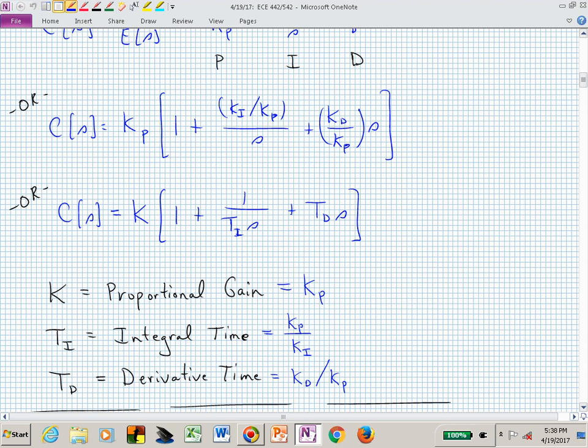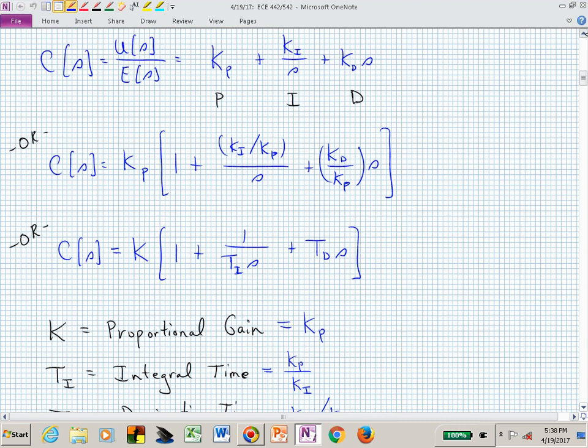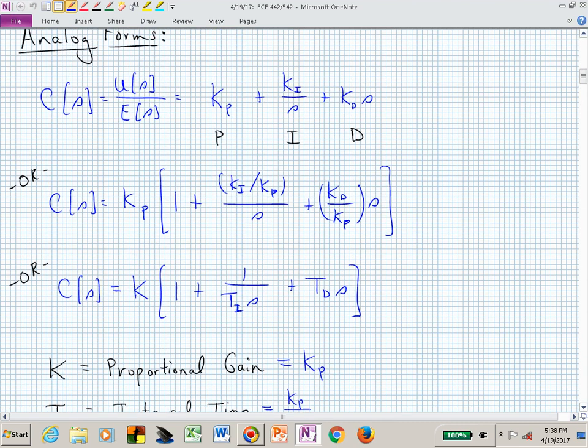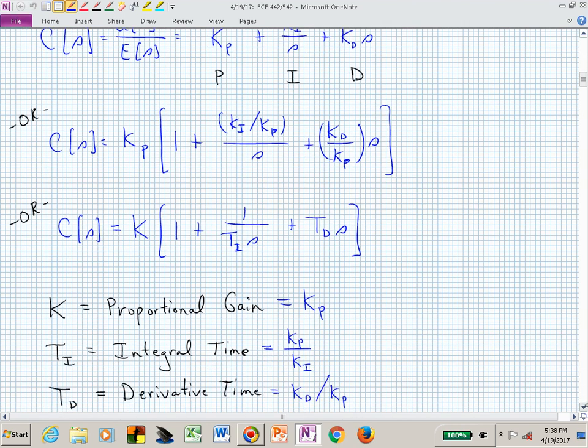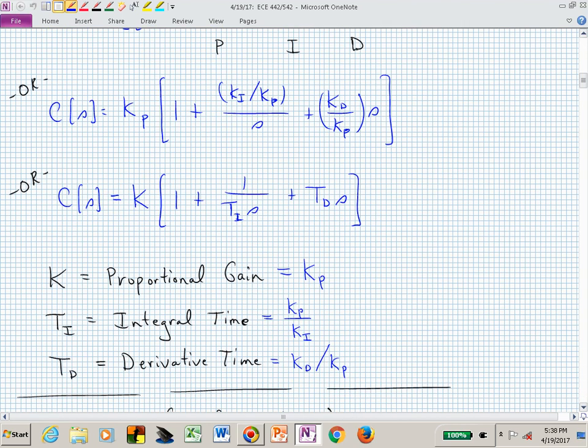So now K sub P would be probably dimensionless, and K sub I, if you looked up here, K sub I would have the same units as S. K sub I is like a frequency. And that makes sense on down in the expression for T sub I and T sub D. So everything should be consistent in terms of understanding. But what you want to take away from this is just, we still have three adjustable parameters, a K, a T sub I, and a T sub D.